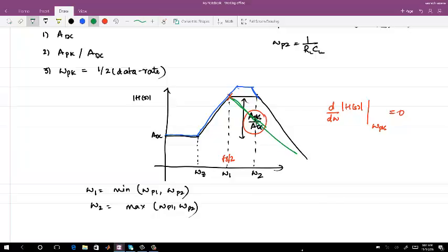Both the frequencies are the same, so you cancel the zero and you have the pole. But this is again a Bode plot. What will actually happen is, if you put them at the same frequency, you will have something like this in a real system. Once you get this, you will say I will shift it, and then I can find it from that. You can always try it that way, but that is more of an iterative process to get the right frequency.